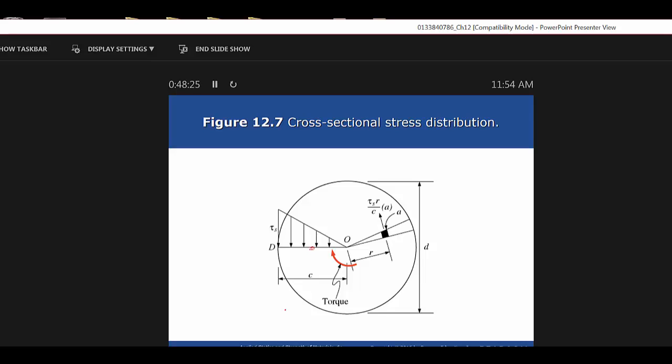If you will, but graduated down. And again, once we get to the center or to the axis of the part, there's no shear stress. There's no torsional shear in that at all. And in fact, it doesn't move either when you get in your mechanisms class.